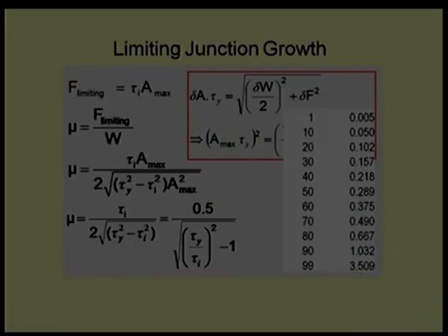This is very close to what we got from experiments. Experimental results show that when two soft materials are used, their interface shear strength will be very high, almost equal to the shear strength of the weaker material, and the coefficient of friction can be very high, maybe 3 to 4, or the 3.5 we are getting from here.